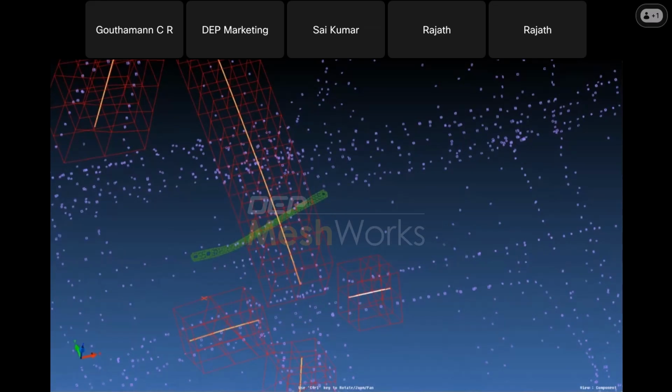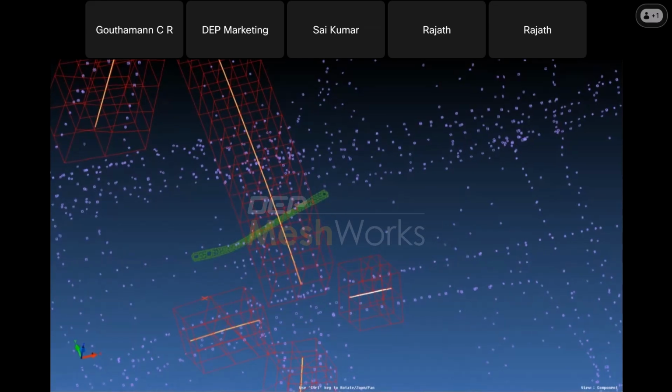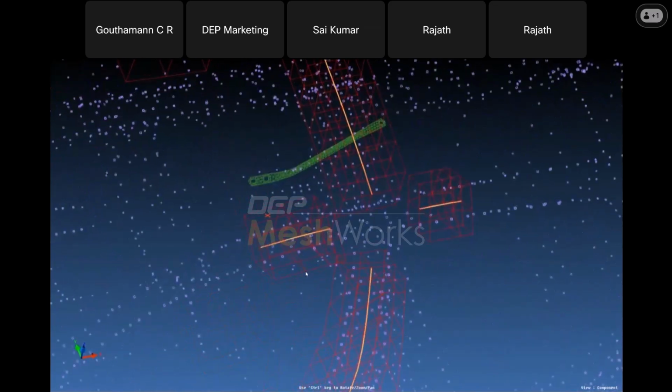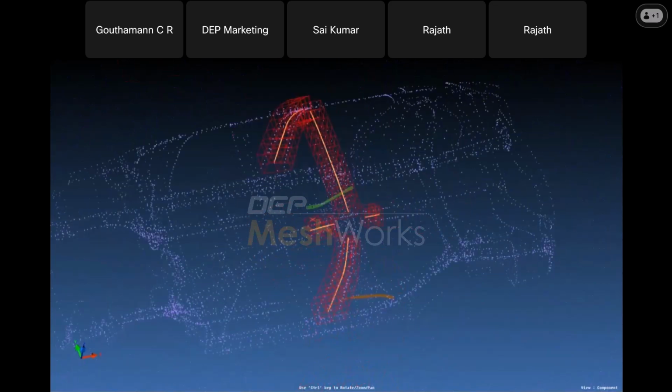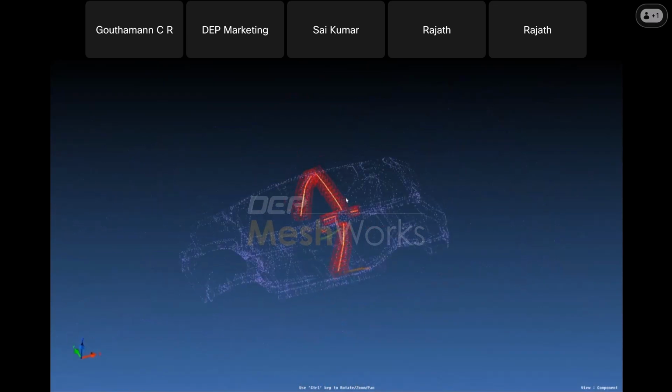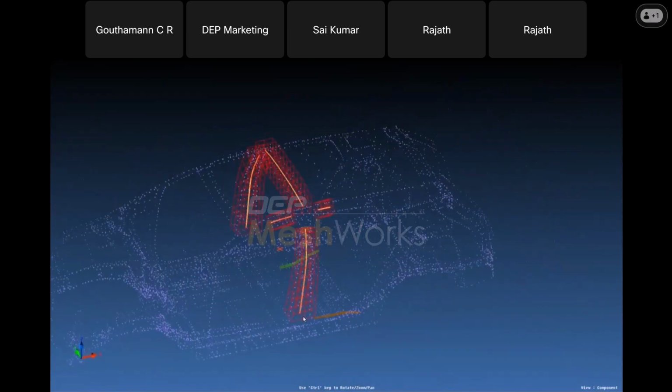Going to selecting the block, selecting the CAD curve, and as this is a smaller one, I'm just going to go with the 2 sections. There. So this way, by specifying the number of sections, we have the control over how many sections we want for any particular part. If it's a bigger one, we can give more number of sections.